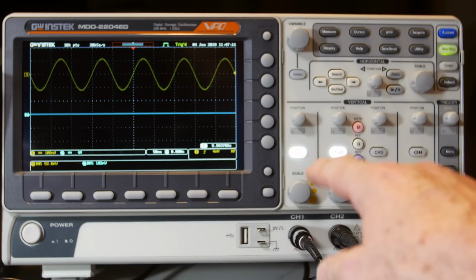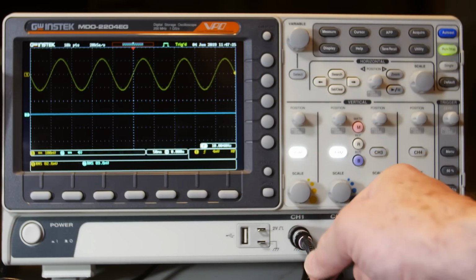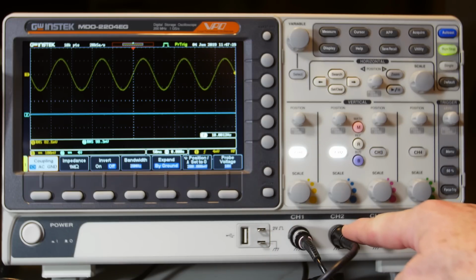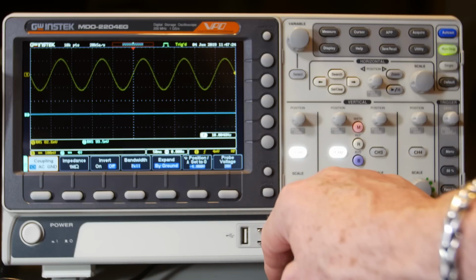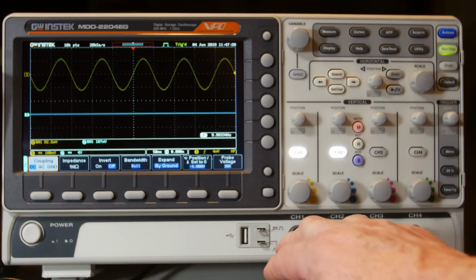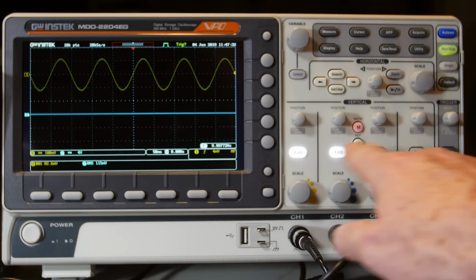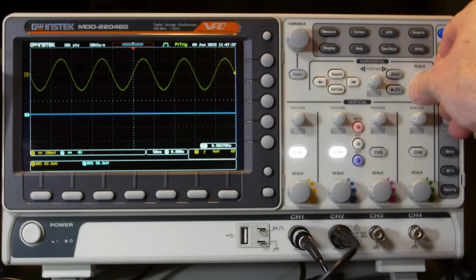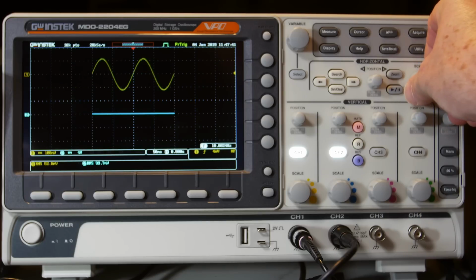For the scope setup, I've got the input voltage coming in here set at ×10 right there, and the differential probe on the output right here ×20, and you know, DC coupled. Both of them are DC coupled, so there we go. And then this scale here I'll be changing as I change frequencies, so we can keep the waveform in view.